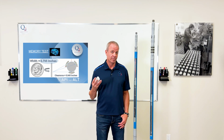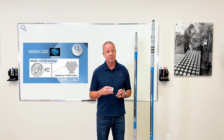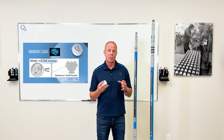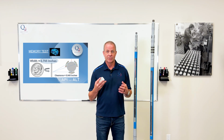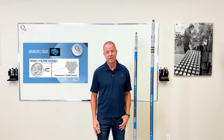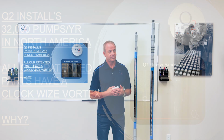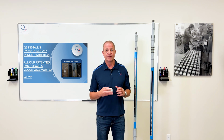Now alternative pattern balls, which are just smaller balls, we run those actually a little bit more because they give us more space in our pump. We can only run these alternative pattern balls with the Vortex style pump, because if you don't, you'll see the damage that it does to the pump in one of the videos coming up pretty soon. Q2 installs about 32,000 pumps per year in North America, although I think it's around 54 pump shops now in every major oil field.